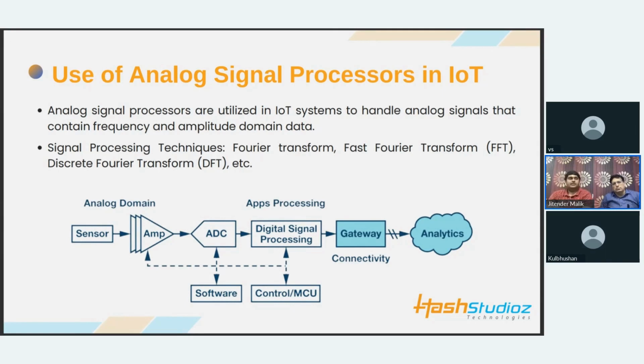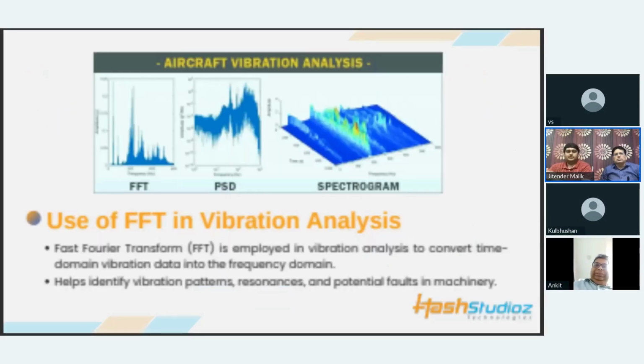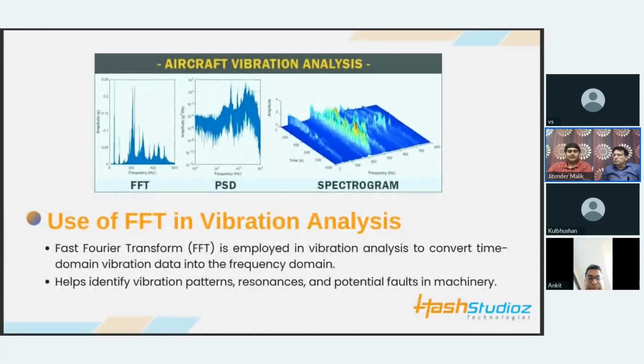Also, we are doing a lot of work into digital reading of sensors. Currently we have gateways that can read 5 and 10 discrete inputs, and the sampling frequency can be as low as 20 ms. Although we cannot process the network transmission at that speed, what we can do is process that particular signal on the device itself and then transmit the data out onto the servers.